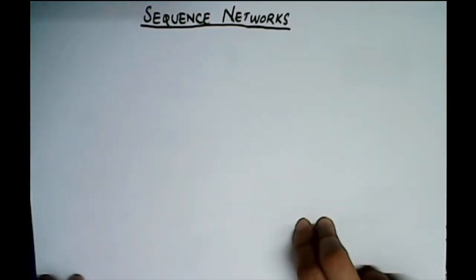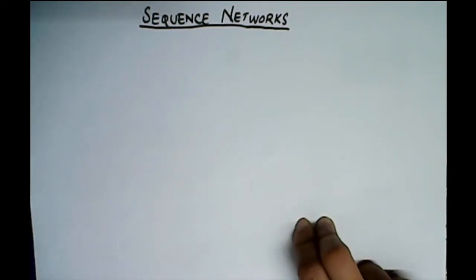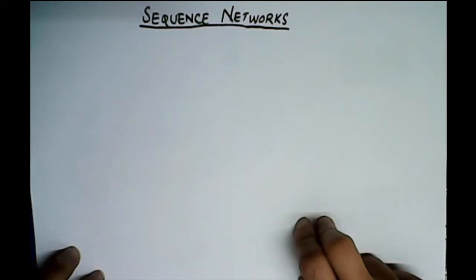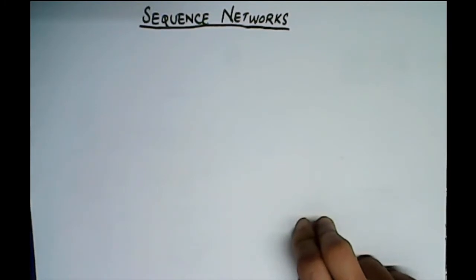Now we already know that there are three currents and voltages present in the system, like positive, negative and zero sequence values. So basically sequence network focuses on drawing separate networks for the positive sequence, negative sequence and zero sequence, because we have already discussed that if the system is ungrounded, there is no neutral, or if there is a delta connection, right, then the zero sequence current will not be flowing.